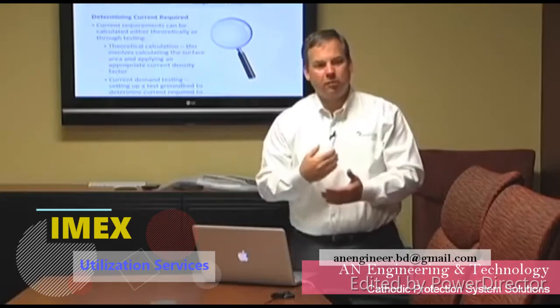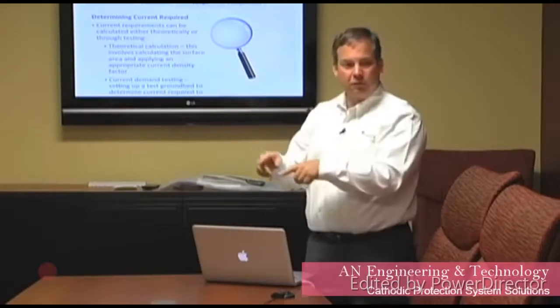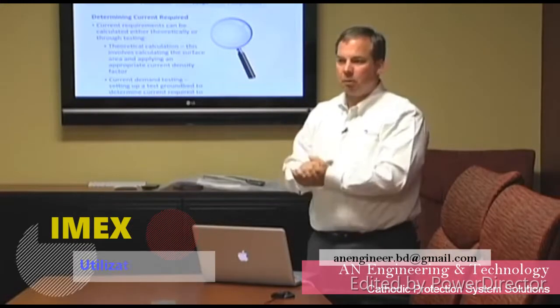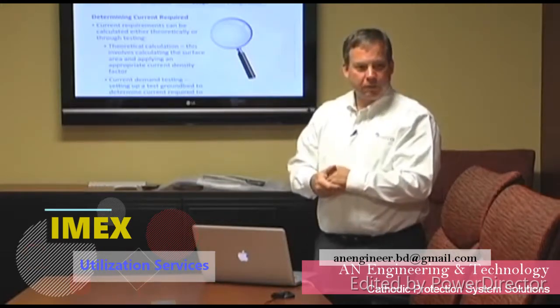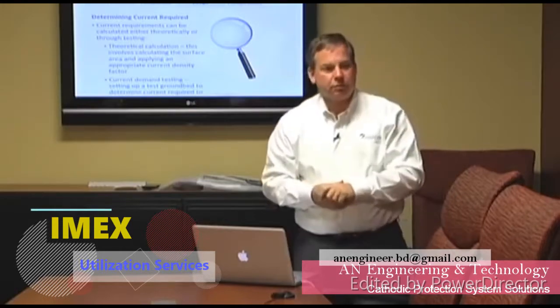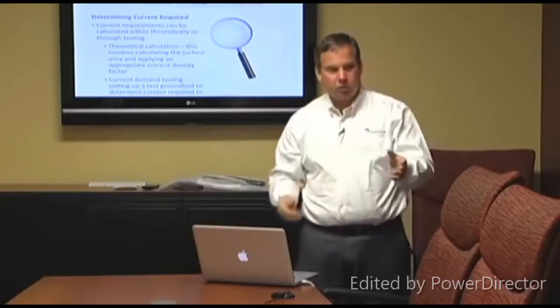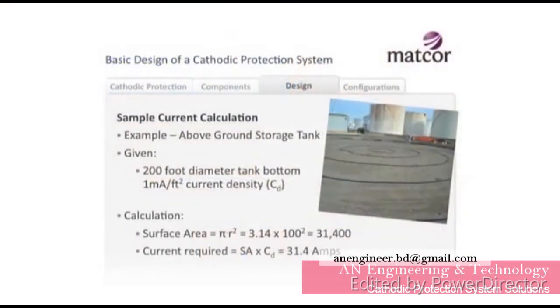Okay, we know that if we put so much current per square foot of surface area onto a carbon steel structure, that we're going to get enough polarization. Is it the surface area of the structure you're trying to protect? Yes, the surface area of what we're trying to protect is the biggest issue. So I'll give you a sample calculation here. I talked about an above ground storage tank, again, a very common CP application. MatCor has systems that we sell for this.